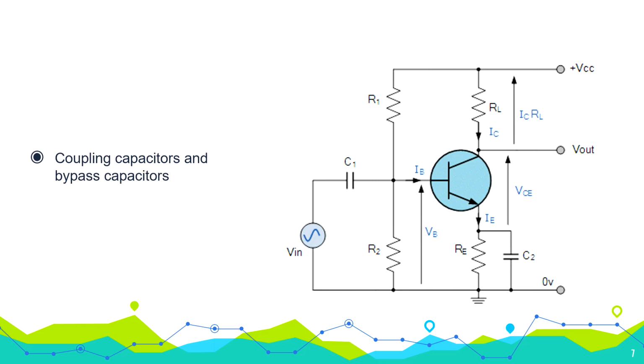This input and output pair of capacitors allows AC signal to flow, and it blocks the DC signal, acting like a filtering circuit. While the second type of capacitor is called as bypass capacitor, which is connected to the emitter terminal of the circuit. This emitter capacitor is used to increase AC gain in the circuit so as to keep the circuit in the biasing state.